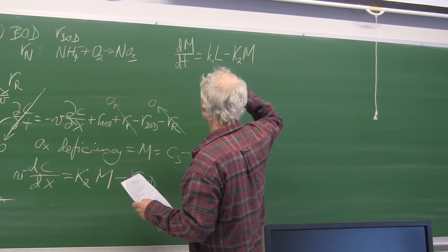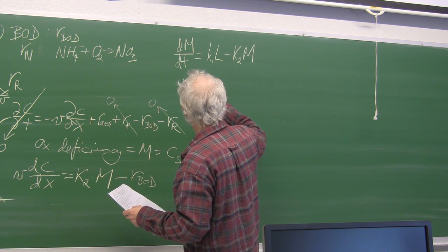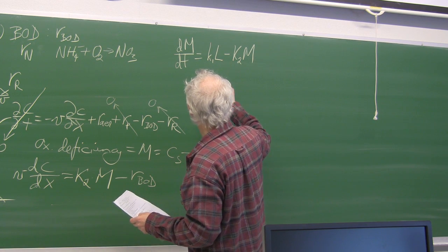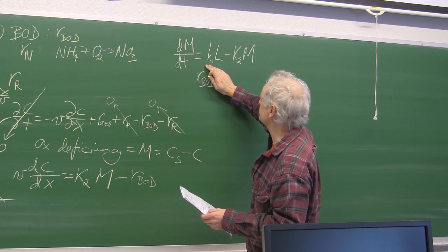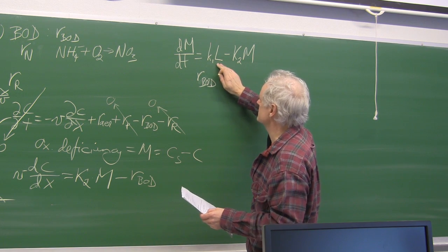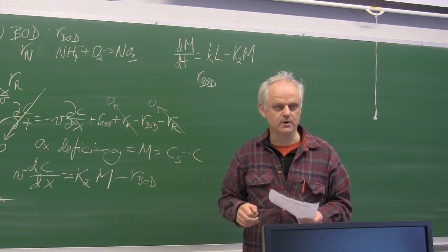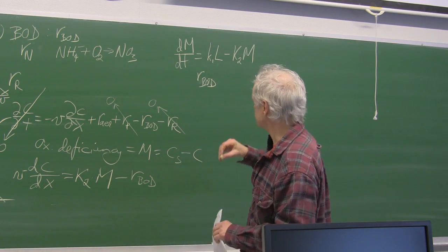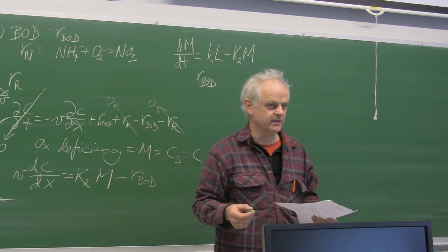And I guess I forgot to say this is rate of BOD, which is often modeled just as a coefficient times the BOD in the water. So L is an expression for the measure of BOD. And BOD is just similar to the COD that we've been working on in our biogas model.